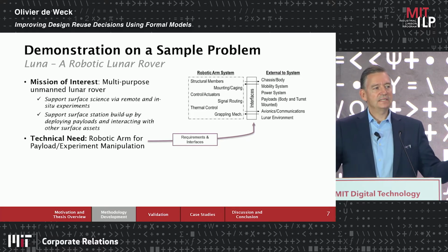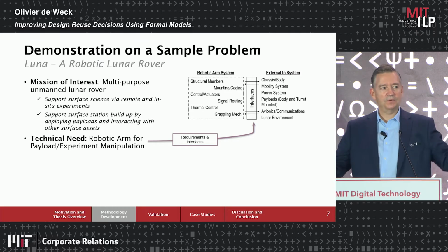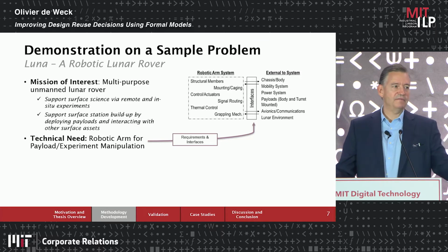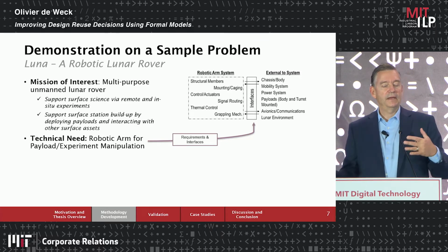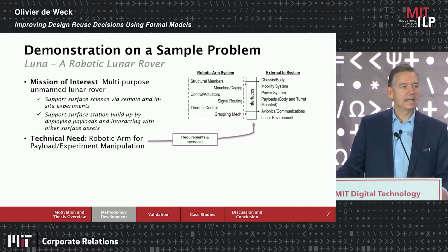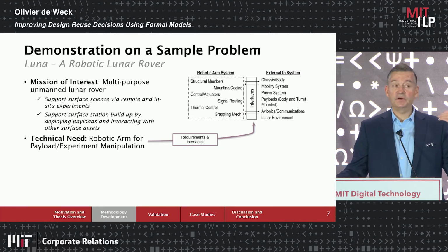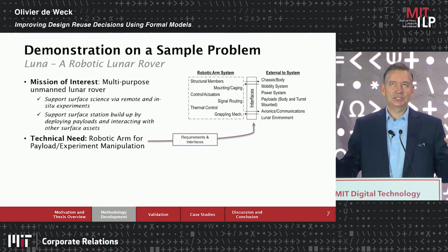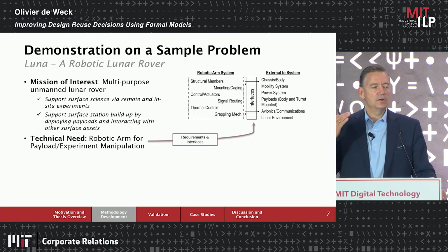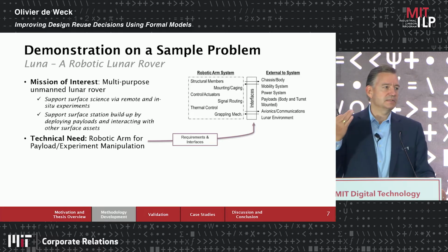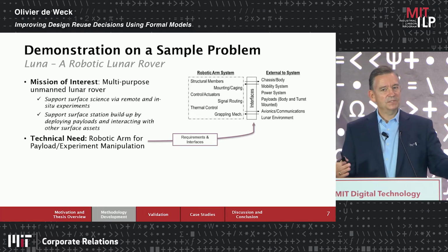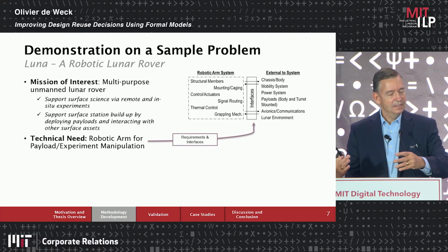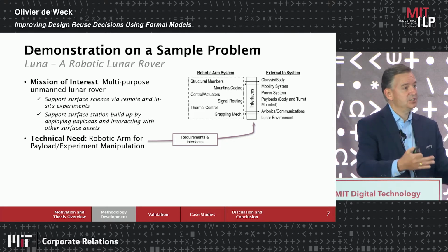So if you design something for Martian gravity, picking up rocks or whatever, that would probably be over-designed by a factor of 2 just from a gravity perspective for the moon. And then what's another big difference? Atmosphere. So Mars has an atmosphere. It's very thin. It's like 1% of Earth's atmosphere. It's CO2, 95% carbon dioxide. And the moon has essentially no atmosphere. So it's a very harsh thermal environment. So the thermal environment is much harsher. So from a gravity perspective, the moon is easier than Mars. But from a thermal perspective, the moon is more challenging than Mars.